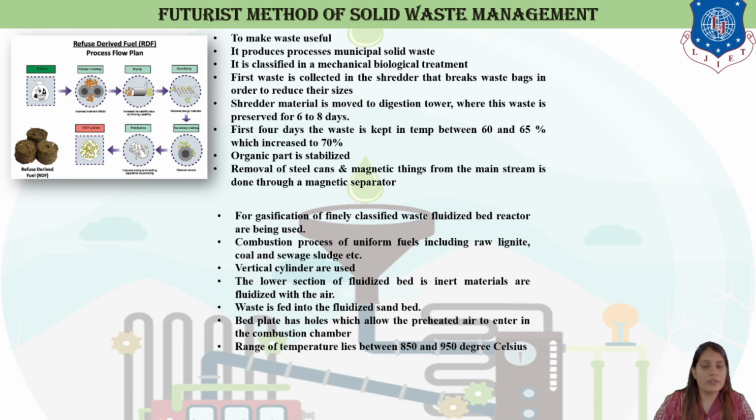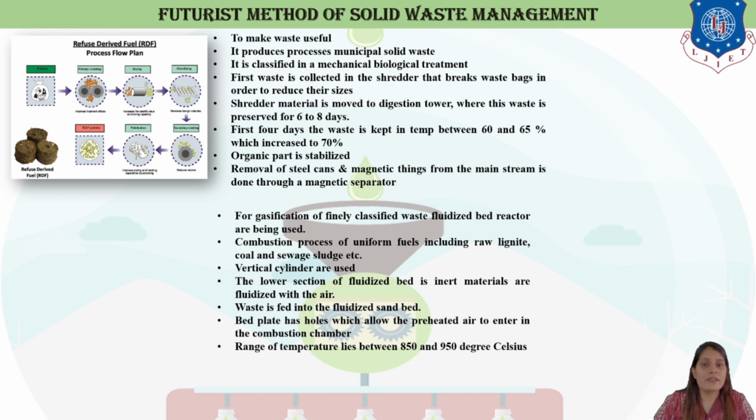Firstly, the refuse is used. Then we have the primary screening, the drying of it, and classifying it. So basically we are segregating the waste because we need to make the refuse-derived fuel. You can see that in the primary stage it is crushed, then we do the drying process, then we classify it. What is required in the primary goes to the secondary, and again purification is done, and hence we get the RDF pellets, and then we have the refuse-derived fuels.